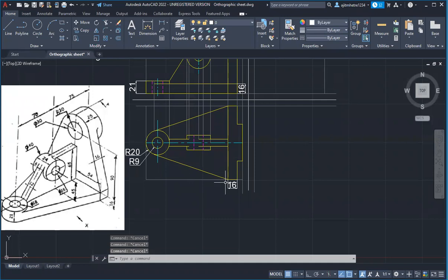अब सुनो बराबर से. This is the hidden line. ये center जो है, center circle, ये जो circle. This circle I have to make it. When you see from a top view, you are not able to see this circle. So the circle is having a diameter of how much? 30. ठीक है? तो center line से 15 above and 15 below. So let's start with that. So 15 above and 15 below.